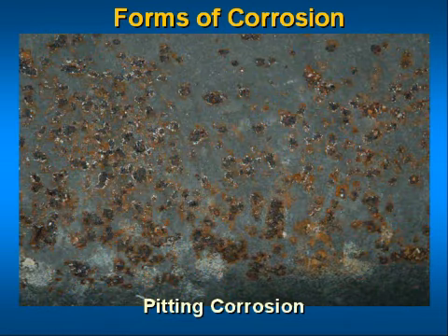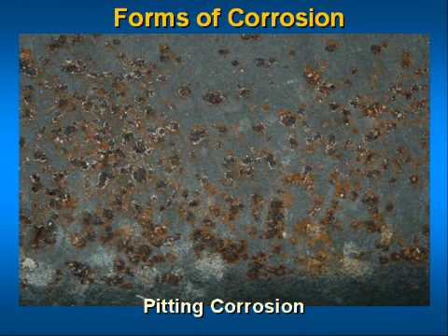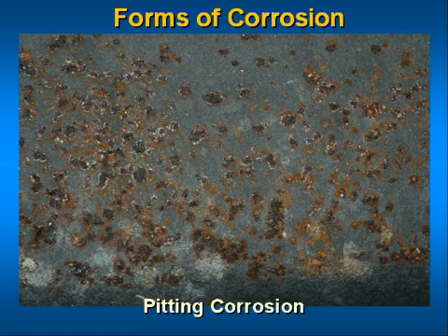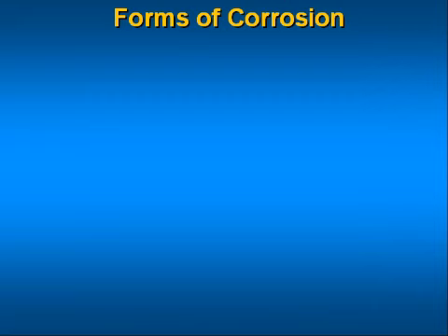Pitting corrosion. Pitting corrosion is localized corrosion that occurs at microscopic defects on the metal surface. The pits are often found underneath surface deposits caused by corrosion product accumulation. The rust bubbles or tubercles on the cast iron indicate that pitting is occurring. Researchers have found that the environment inside the rust bubbles is almost always higher in chlorides and lower in pH, which means it's more acidic than the overall external environment. This leads to concentrated attack inside the pits.